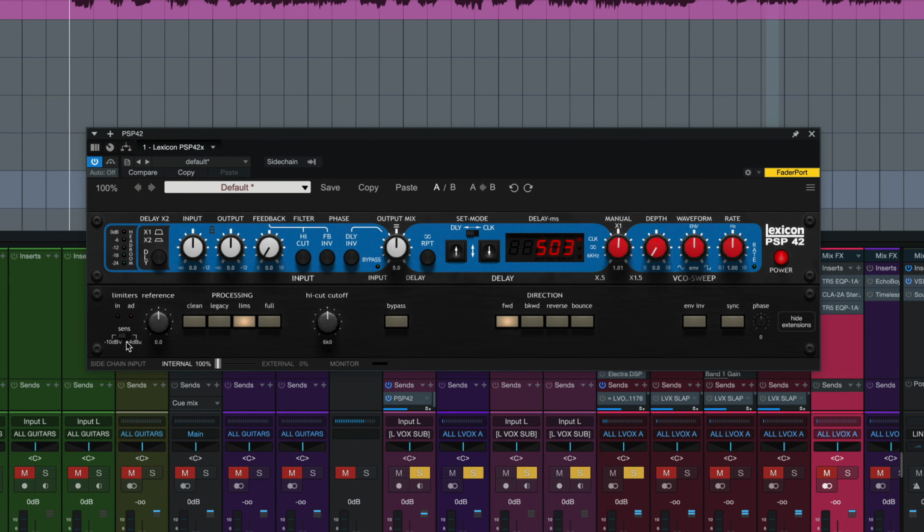The sensitivity switch right down there switches between the semi-pro -10 dBV or the pro +4 dBu reference, which allows you to kind of set the headroom of the processing along with the reference knob. And this can be also used to overload the circuit, which is really cool. The reference knob right next to that sets the reference level for the saturator, limiters, and converters. So a lower reference level equals a greater level for the limiters, saturators, and converters, driving that signal even harder.